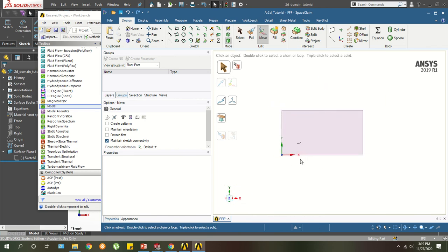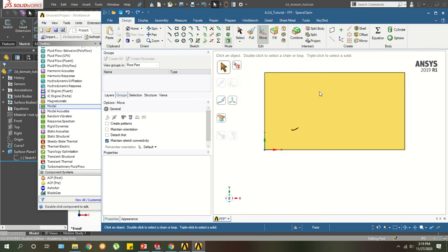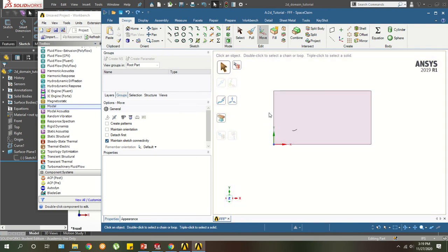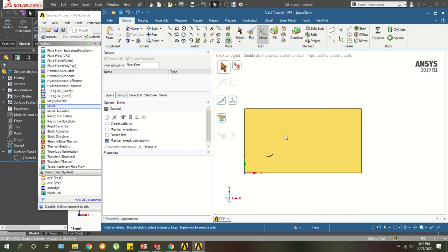The reason we're doing this, we need to set up named selections. So basically, you see the airfoil is facing this way, right? So this edge is going to be the inlet to our fluid domain. This edge will be the outlet. So we're saying the airflow goes left to right. Maybe we'll set this as the ground, a moving ground, and this top surface will be a free surface, which will use a symmetry function for that. But you need to tell the program what to expect later down the road. And so that's what we're here for.